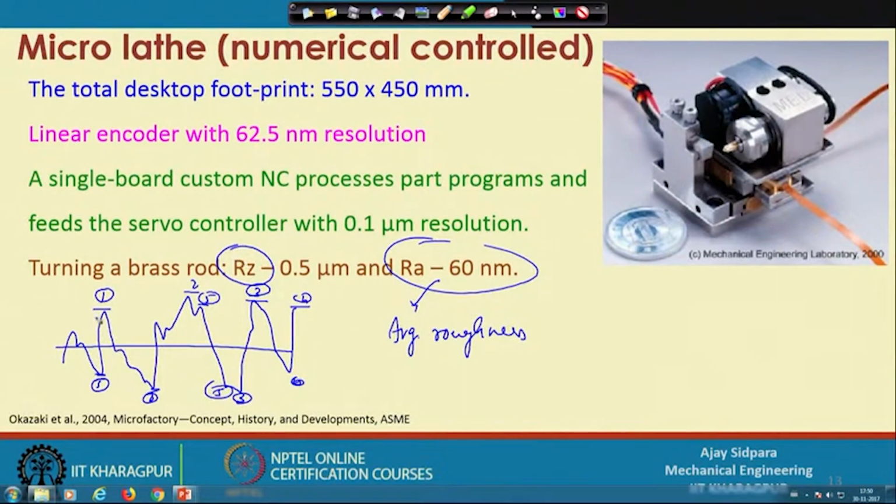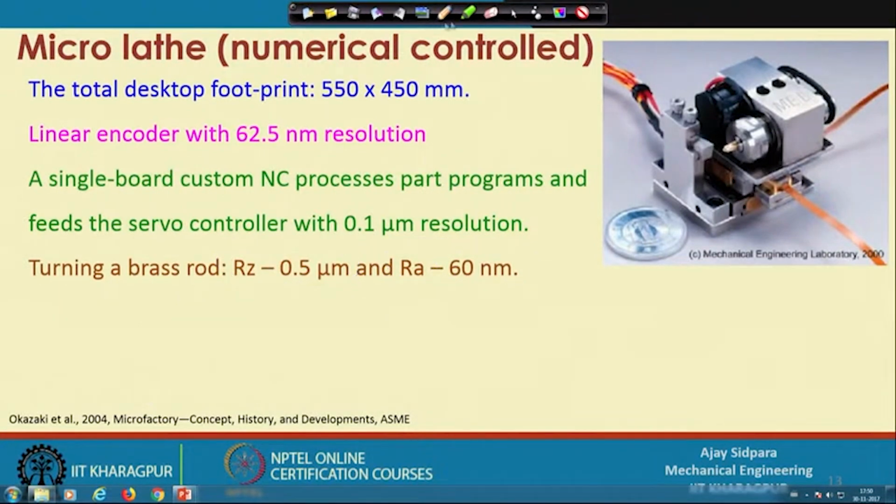So, you can see that this is talking about the highest values only. So, it has a higher rating here, that means the value of Rz is always higher than the Ra value, because Ra is the average. All the small peaks will also be counted in the calculation of Ra. So, if you want to see the actual picture of this part, then Rz is the right parameter compared to Ra, because many different surfaces have the same Ra value, because it is an averaging value of many components.